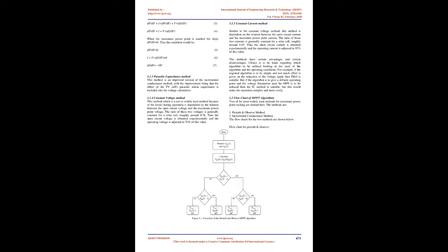2.2 Photovoltaic modules. PV cells are the basic building blocks of PV modules. For almost all applications, the 1/2 volt produced by a single cell is inadequate. Therefore, cells are connected together in series to increase the voltage. Several of these series strings of cells may be connected together in parallel to increase the current as well. These interconnected cells and their electrical connections are then sandwiched between a top layer of glass or clear plastic and a lower level of plastic or plastic and metal. An outer frame is attached to increase mechanical strength, and to provide a way to mount the unit. This package is called a module or panel.